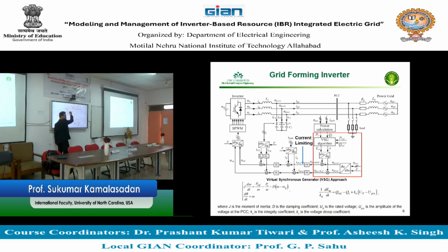So this is basically how fast the frequency goes down. If you control this rate, you can control this point. If the rate is faster, then it goes down. If you make the rate slow, then this point control is not just putting some flywheel or inertia. This point control, emulated inertia, is also related to how fast the rate changes.